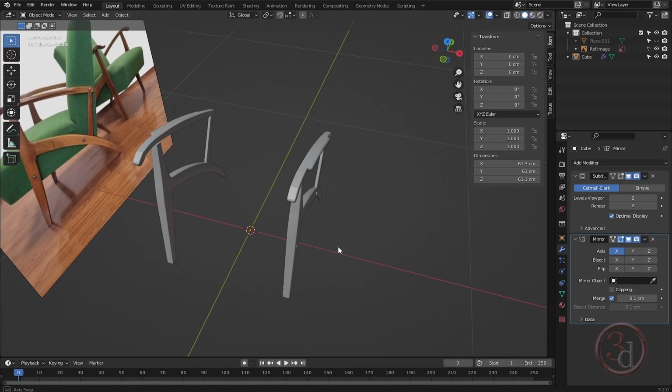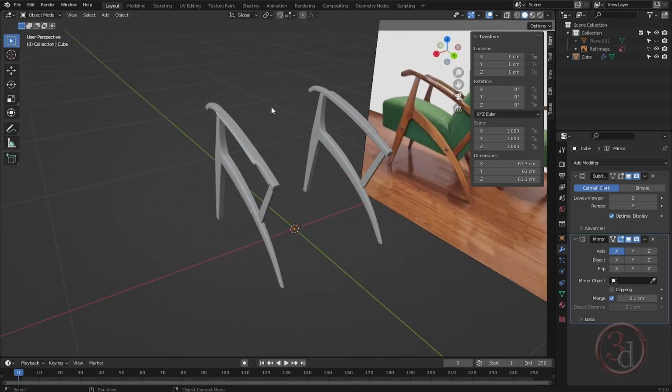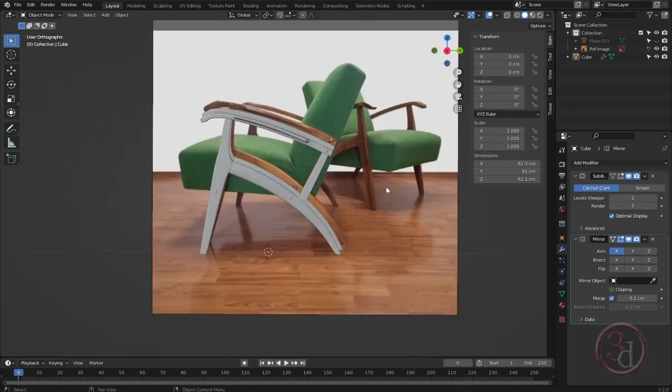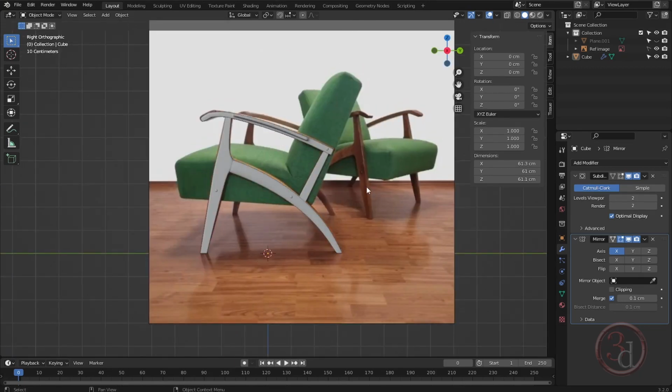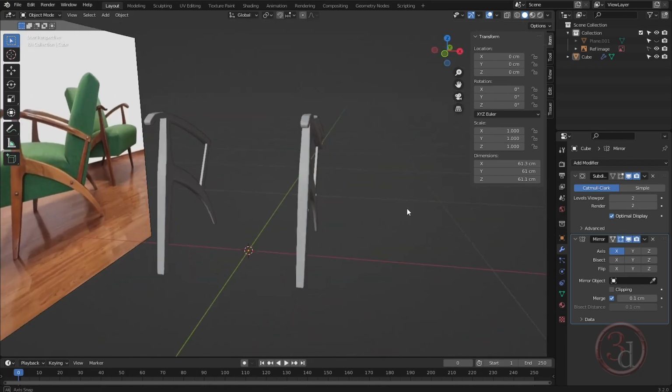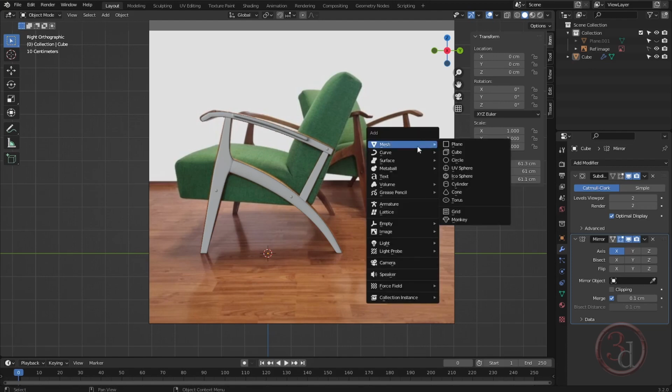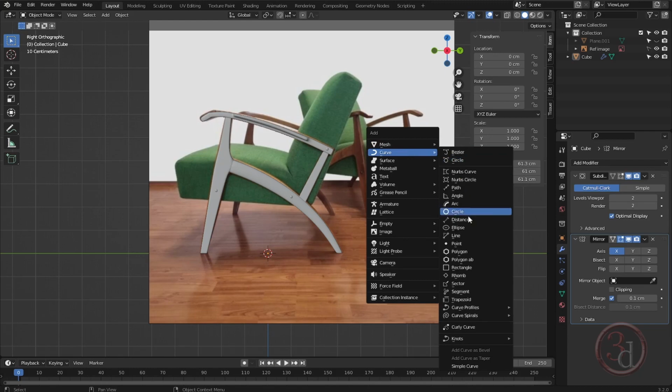So if we hide this box, now the remaining part is in the center, the seating part. So let's begin our seating part. There are multiple ways to do it. The easiest way I would like to do is by pressing Shift A, and I will create a point.